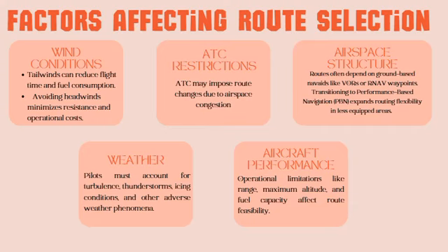Airspace structure. Routes often depend on ground-based navaids like VORs or RNAV waypoints. Transition to performance-based navigation expands routing flexibility in less equipped areas. Weather: convective activity, thunderstorms, turbulence, or hail conditions are avoided by choosing alternative routing. Real-time updates help pilots and dispatchers adjust the route in flight.